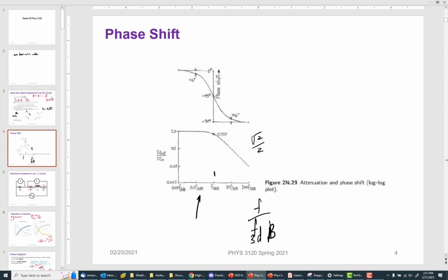Hopefully we kind of understand why the output changes, because the capacitor and then in the oscilloscope lab the inductor are both frequency-dependent resistors, variable resistors. So instead of turning a knob like a potentiometer, we change the frequency and we change the resistance of a capacitor or an inductor, or in a general word, we change its impedance.